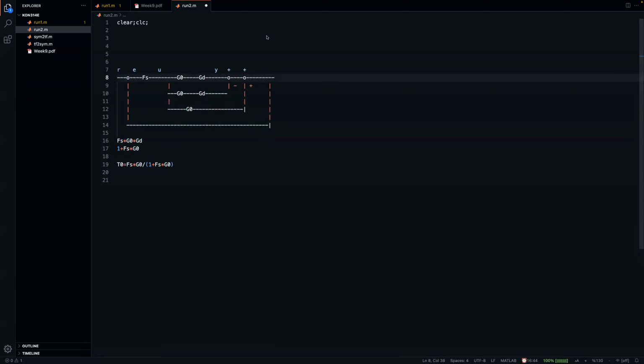equal to 0. So what you should do once this lesson is over is open up Simulink and create a structure and connect some scopes maybe here, and run a simulation on that. If they are matching each other, you will get a 0 signal out of here. This portion here is basically constructing the non-delay output, which is the predicted output without delay. It feeds that back, but the overall delay is still in the feed-forward path. Therefore, it will be delayed by 2 seconds.